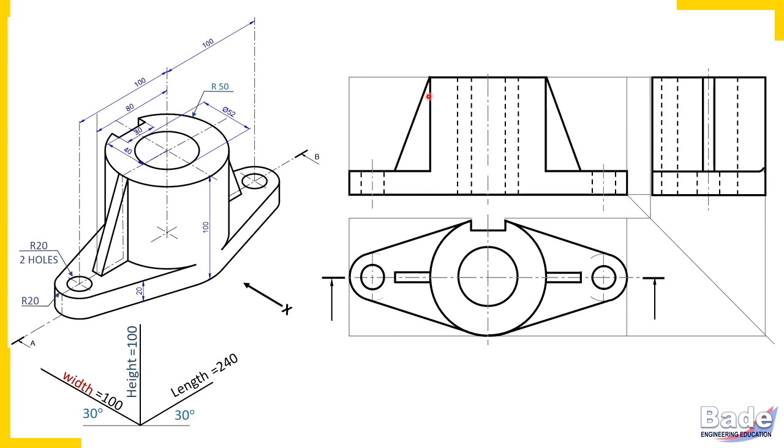Remember, in a sectional view, the boundary between the two parts which are attached to each other or which are in contact, for example here this is the cylinder and base plate. Now this edge here I have erased, I have removed. In sectional views, the two portions which are in contact, for example here the cylinder and the base plate, the boundary between the two will not appear.